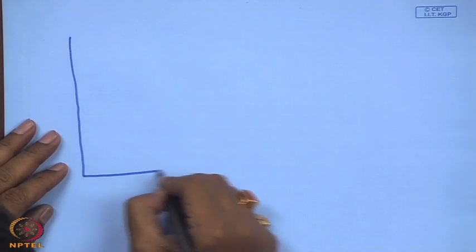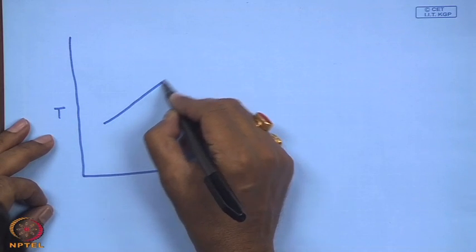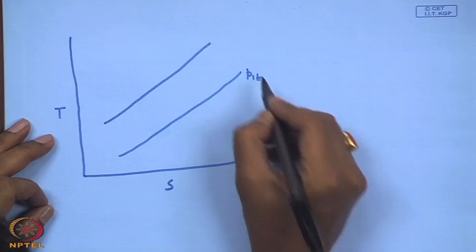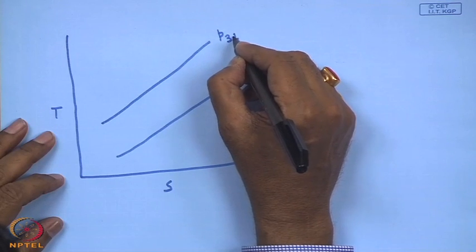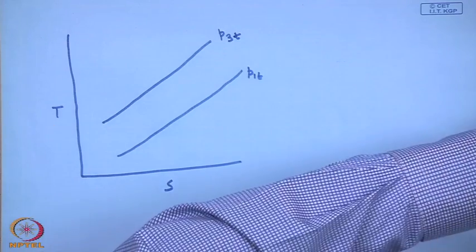In the last class, we were discussing the work done to the fluid and the pressure rise. Let us continue the earlier discussion a little bit. We were trying to express the compression process thermodynamically in the Ts plane by showing two constant pressure lines. One is the total pressure P1T at the inlet to the compressor, another is the total pressure P3T at the outlet of the compressor, which includes the diffuser too.